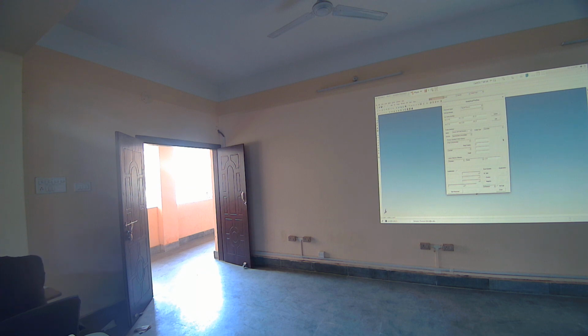Need to name here as Gaussian for source. The profile type I have selected here is Gaussian type. There are 3-4 options here: Gaussian type, error function you can select, and multi profile. So I am selecting Gaussian type here, right?